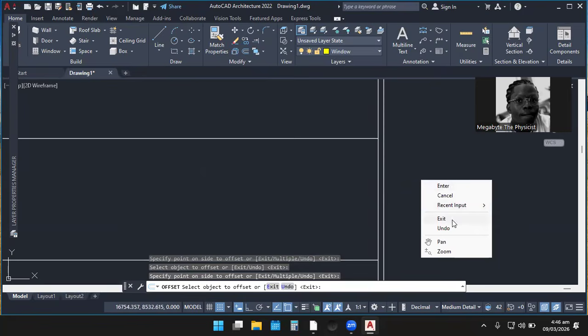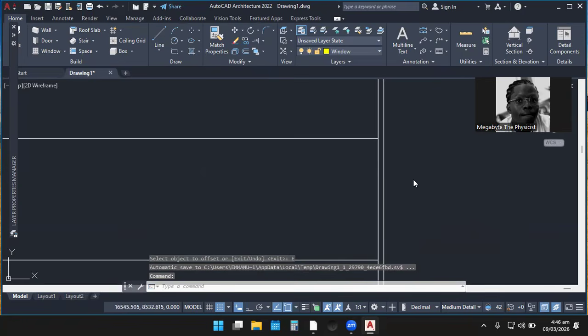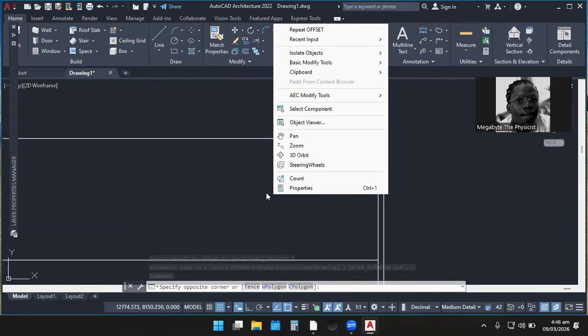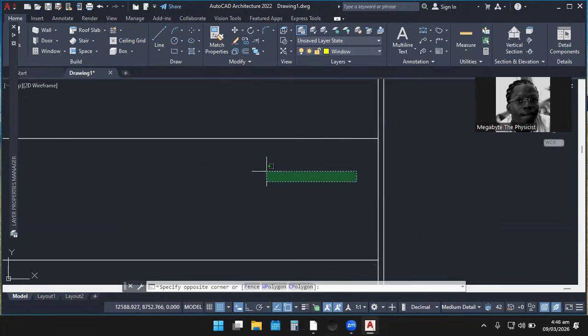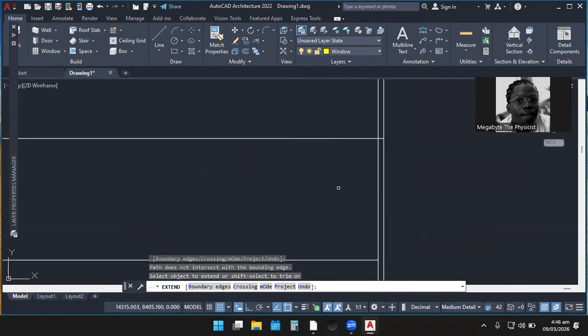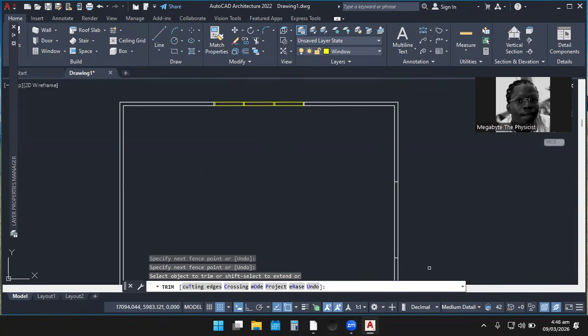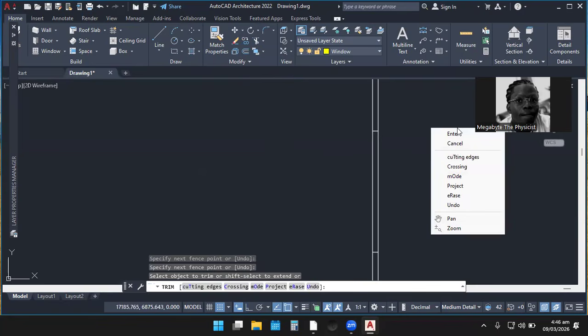Let me escape this, and then we use the extend command. So this is the extend over here. If you come to this, you see extend. So we extend these 2 lines. We extend these 2 lines. Then now we can trim it. Let's trim it. Come and pick trim over here. We trim the 2. So we let our main focus be on here since we are still drawing the window. Now let me remove this.